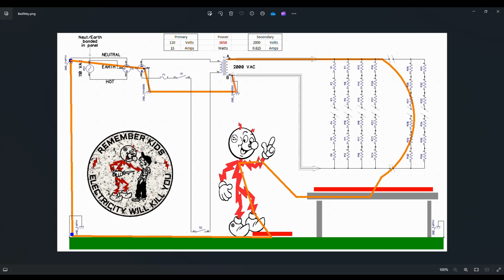It can go directly through, if you're using probes, which is foolish, that leaves 100 and more ways that you can have some kind of a failure that allows current to enter your body. Your arms are particularly susceptible because from one arm to the other, it crosses the chest area.